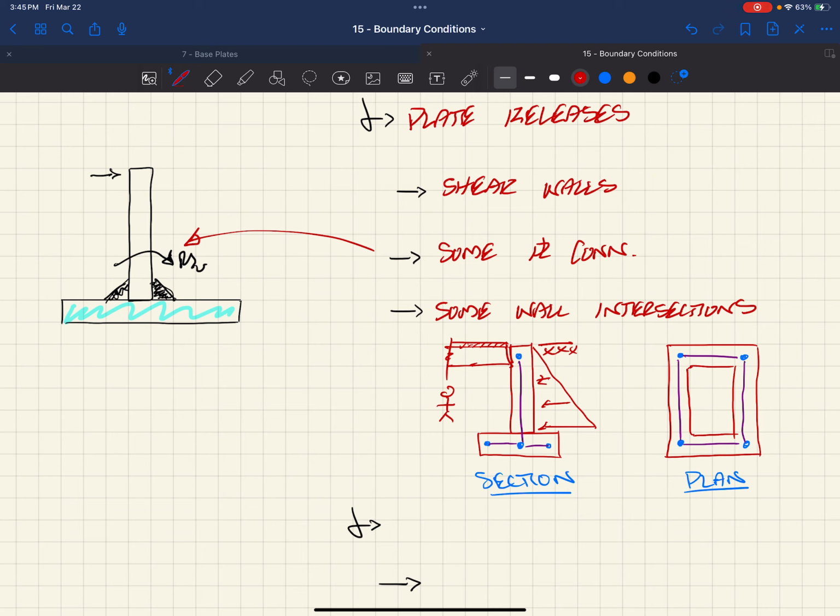It's not super important. But what it does do is it all of a sudden is now making this wall act as though there's a pin up here, right? And so you have the option as a designer sometimes, and it usually leads to a more economical design, that we pin the wall at the top, right? So now the wall cannot push over.